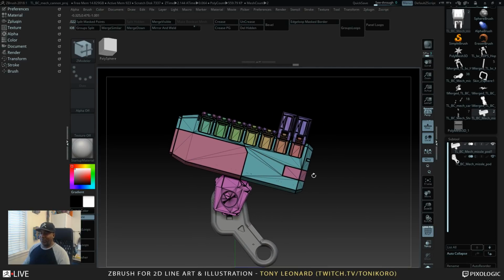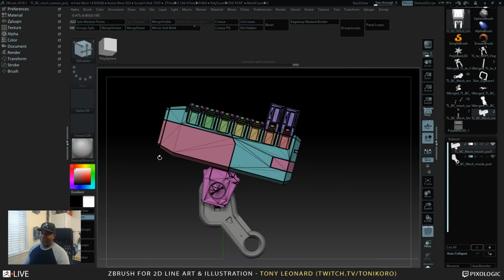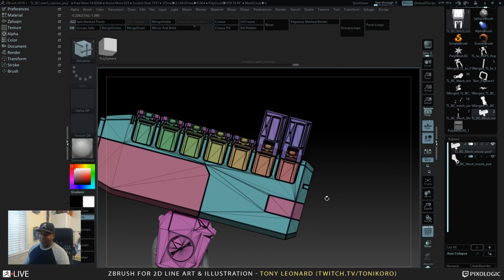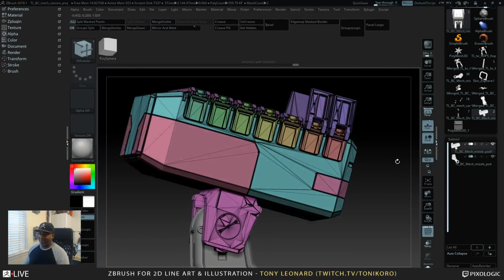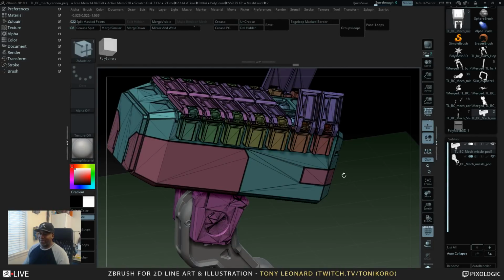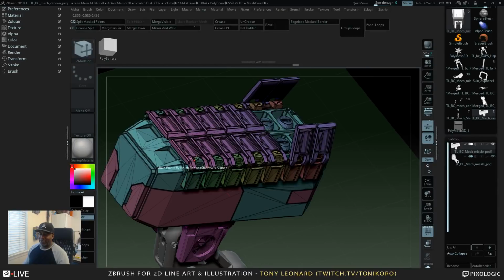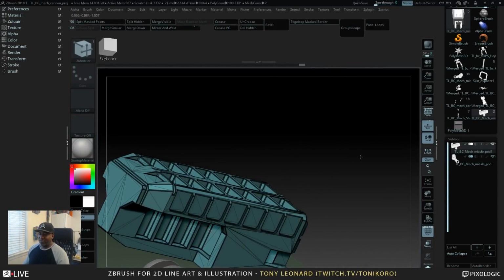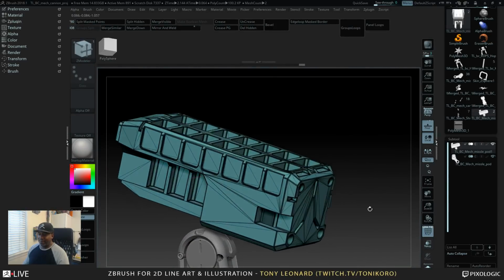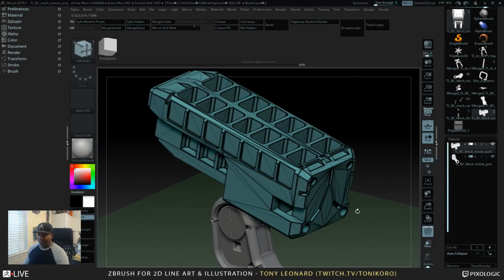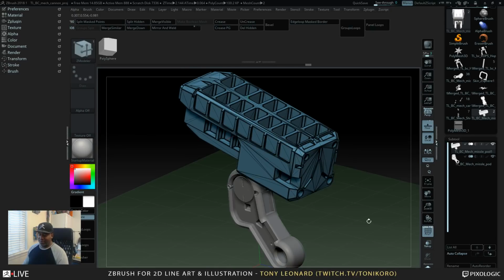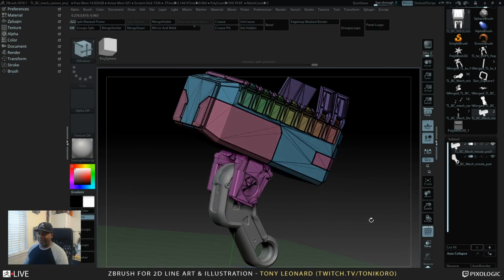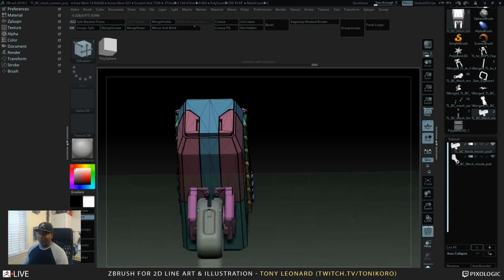Maybe I might want to take it into another app and just add materials for each spot. So it helps really a lot to have definitive separated geometry, or if I have to separate a lot of different pieces, I can make sure that all of these little hinge pieces are in one polygroup, and I can just deselect pieces off and then change their polygroup, right? So hitting something like a Control W, and it becomes the same color. And so now when I come back and unhide everything, that piece is all one polygroup.